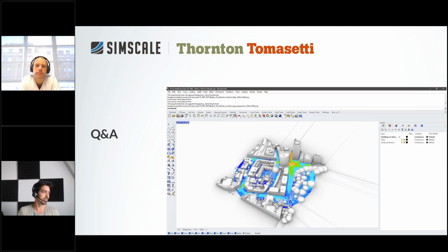Yeah, that's a good question. And sorry, I brushed over it because we're so used to it at SimScale meanwhile that we don't really think about it, but that's a very good question. So to take a step back, the Lattice Boltzmann solver runs on GPUs, graphical processing units, because they're very efficient in computing massive amounts of data in CFD with this LBM solver.